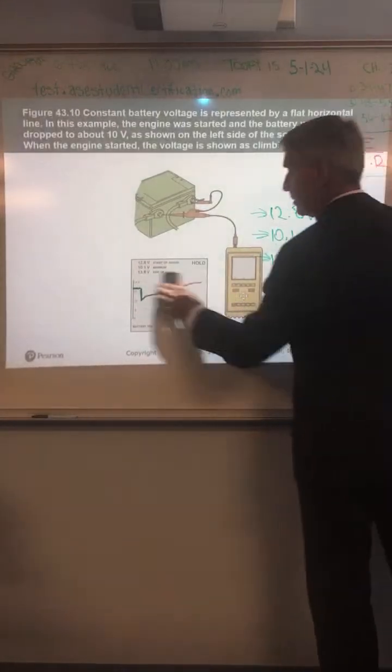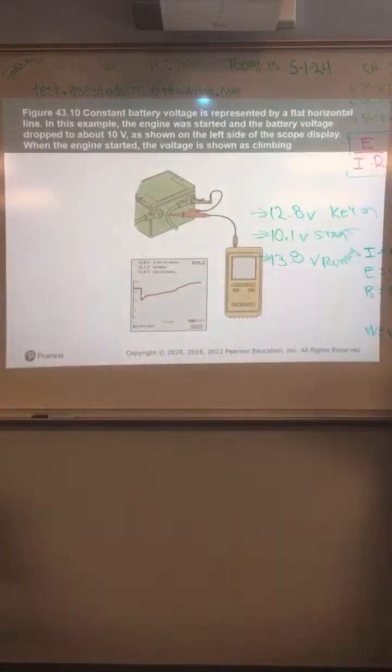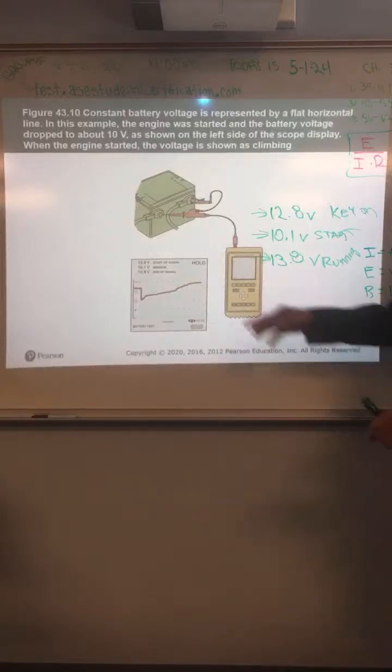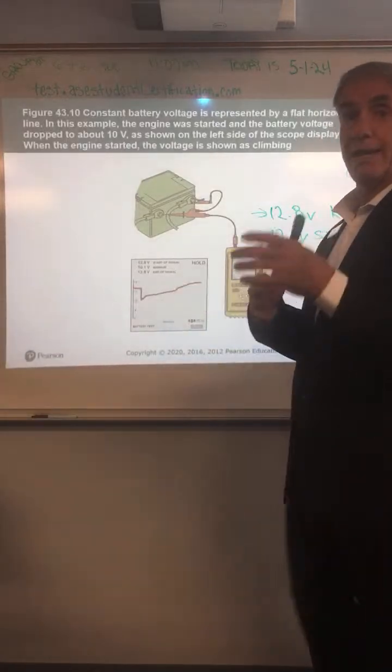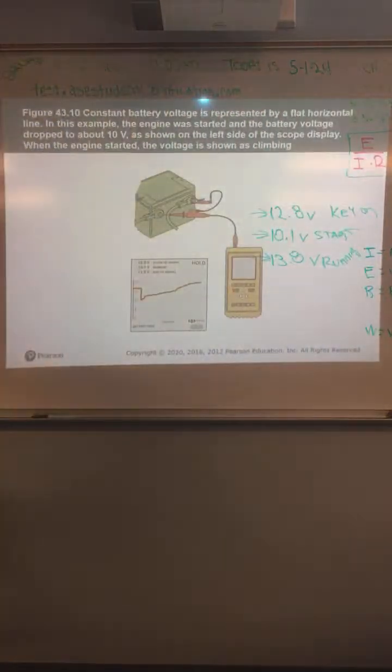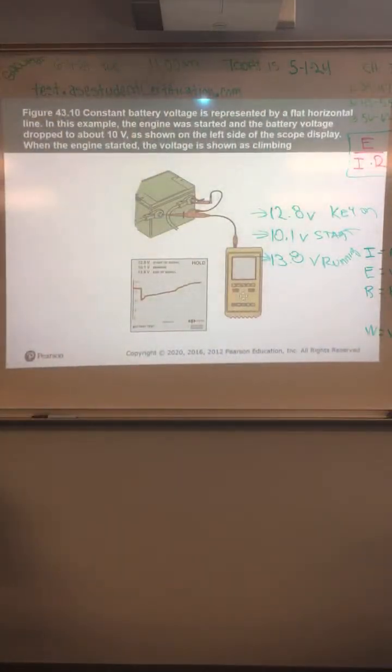The scope gives you the opportunity to actually watch it and see if there was a problem with a circuit or a voltage signal. It would be easier to look at it than to try to catch it on a meter as just a number.